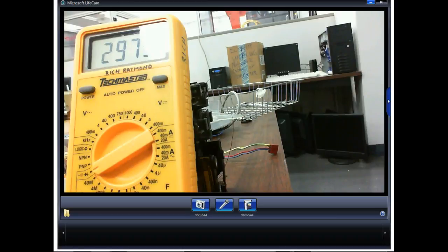This only drops about 700 millivolts. That's rule of thumb. Notice this guy dropped about 600 millivolts. But 700, what's 100 millivolts between friends? And this is with your meter. So that's pretty neat. So this is the way we can check what we call a PN junction.